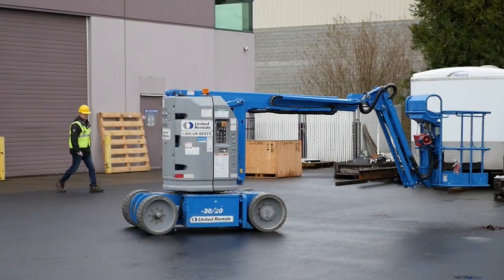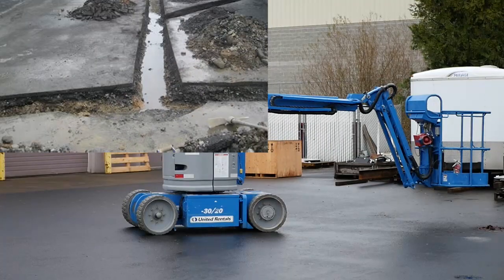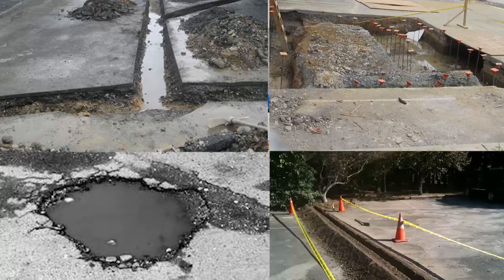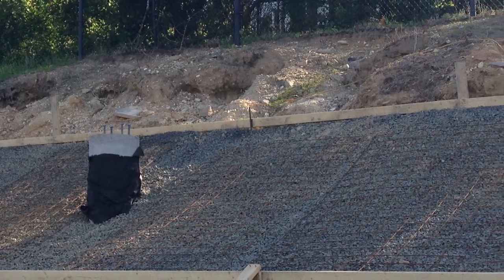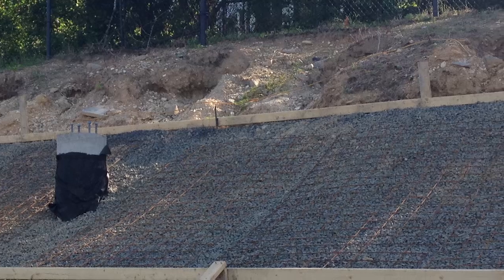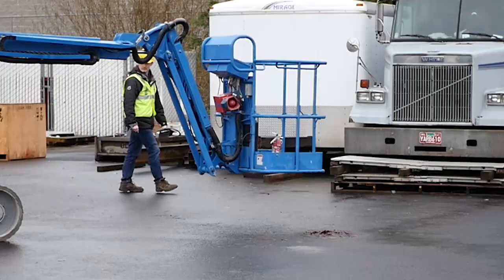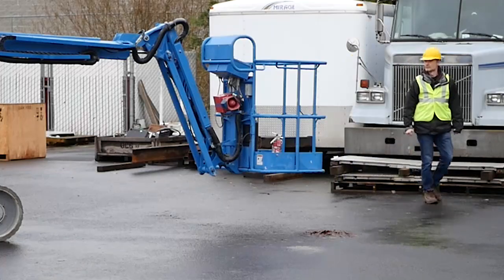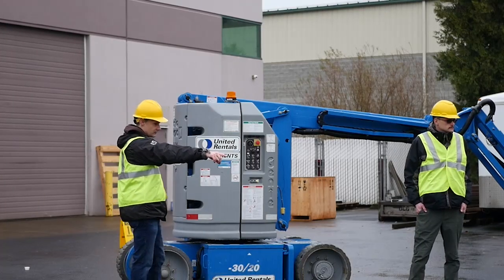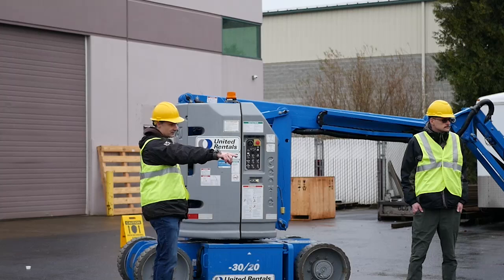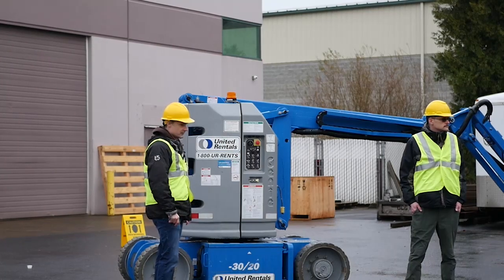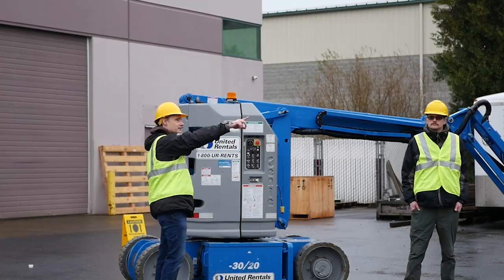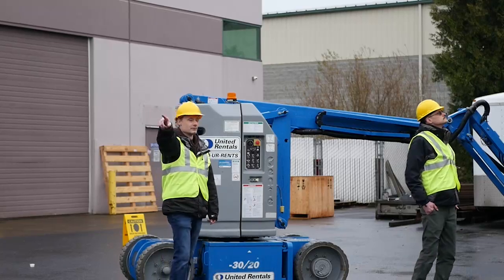Walk the work area and make sure there are no ditches, excavations, holes, or similar hazards. Check for excessive slopes or drop-offs that may cause the vehicle to become unstable. Check the area for loose debris, materials, or equipment. Verify that there is enough space between the aerial device and obstructions around it. Be especially careful to check for electrical hazards, such as overhead power lines.